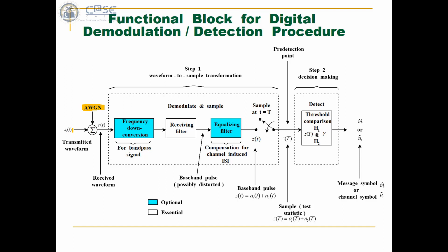i stands for the ith transmitted waveform. We assume we have many waveforms, and the ith one was transmitted at one given time. So r(t) is received, and the transmitted signal will have the impact from the noise in additive form. So r(t) is nothing but the transmitted signal and the noise added on top of it. Then we have the receiving filter, which we derived in the last lecture, that will have the maximum signal component compared to the noise component at the output of that filter.